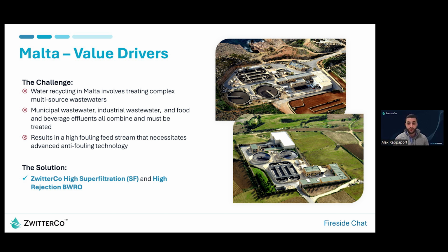And we're also looking at some of the high-strength industrial wastewaters coming from farm and agricultural wastes, from food processing like dairy and tomato production, from breweries, meat and poultry, leachate. There's sort of a collection of different industries that have been known to discharge high-strength wastewater and that can overwhelm the treatment capacity of their centralized plants. And the goal is to find point source solutions that can remove this risk of challenging effluents reaching the centralized treatment facilities so that they can ensure that there are no upsets or no challenges with how they meet their compliance requirements. And in those projects, we're looking at a combination of both ultrafiltration and the brackish RO membranes, providing this unique ability to tackle the high strength wastewaters directly at the source of production.